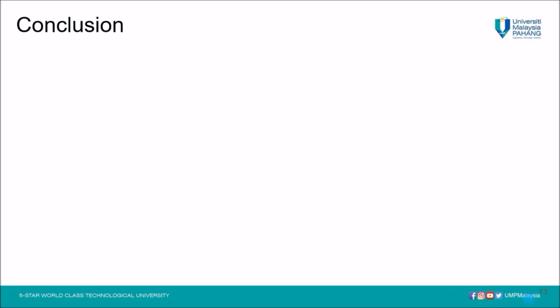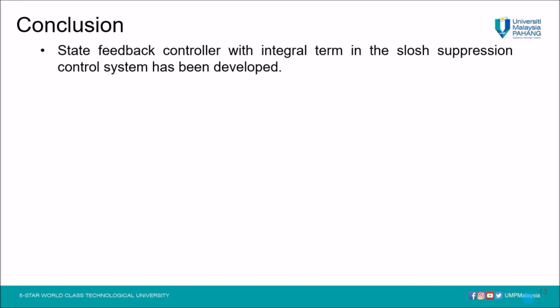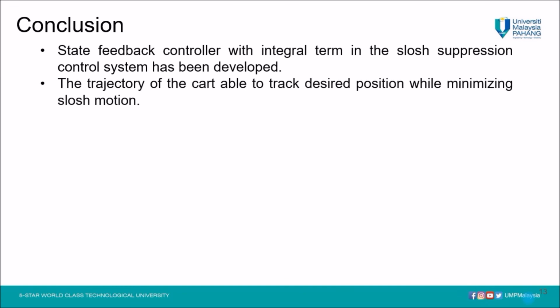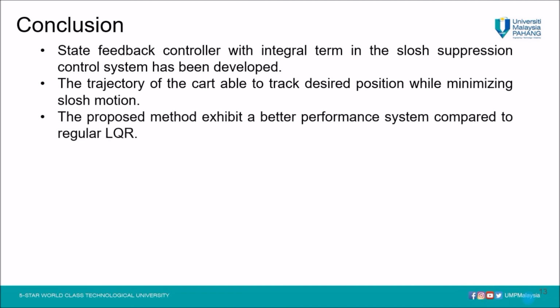As conclusion, a state feedback controller with integral term in the slosh suppression control system has been developed. The trajectory of the cart is able to track the desired position while minimizing slosh motion. The proposed method exhibits a better system performance compared to regular LQR.